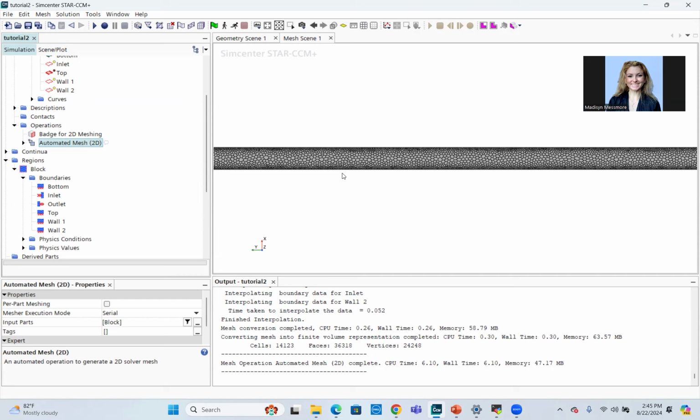And so that's why you usually want to do a grid refinement study and you run it with a bunch of different mesh sizes and then you can plot your result. And optimally, you would want to look for where the slope becomes zero and then you cut it there. Because if you keep going, you risk it coming back up. So you want it to be at that flat bit. And it usually does flatten out. It does. Almost always, unless you messed up something.